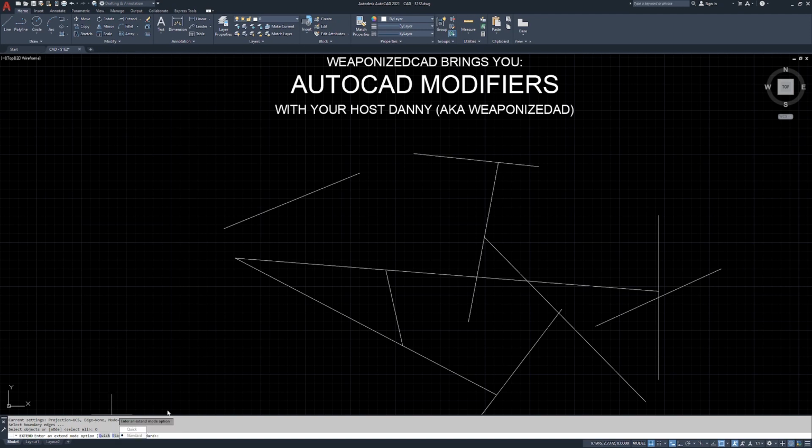You'll notice, even though we didn't change extend to standard, because trim and extend are now combined in a sense, it's going to set both to the same. We changed trim to standard, it changed extend for us. And extend works in the same way. So in quick mode, extend is just going to shoot that line out every time you click it.